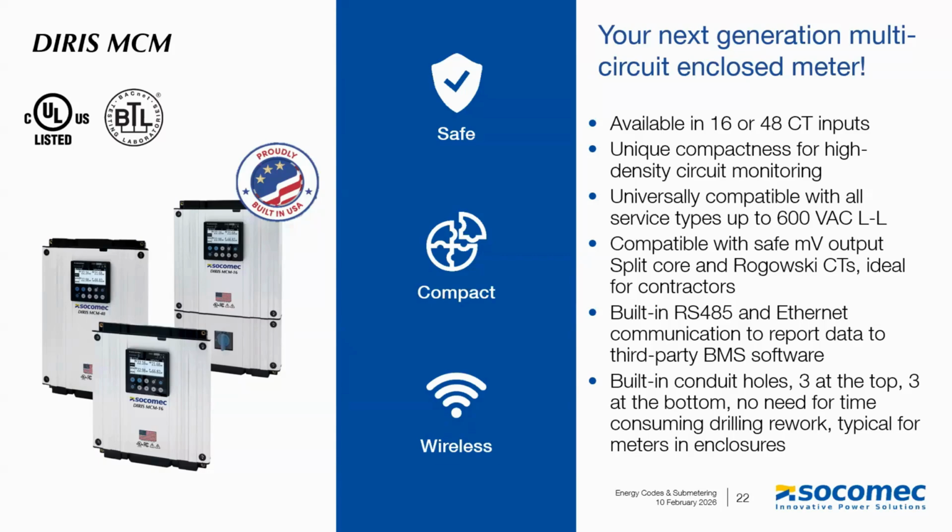The MCM is compatible with all service types up to 600 volts. So whatever the service type, whether it's 120 volt, 277, or 347 volts in Canada, it's compatible with all service types. Same thing with the Digibox A200, by the way. It's compatible with our millivolt CTs. That's a big benefit for contractors as well, as all of our CTs are millivolt based, so they don't need any shorting blocks.